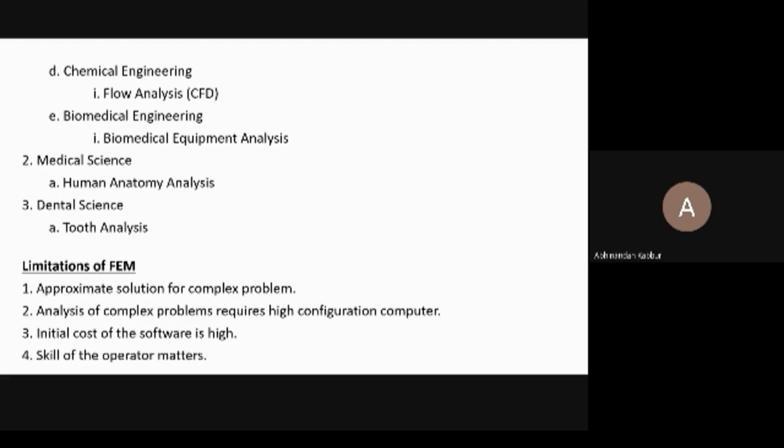And coming to the last limitation of FEM, we require skilled operators. That means see, if you give some input to the computer, it will give the output. The ultimate thing is we need to analyze that output, whether the output is feasible or not. If it is not feasible, what changes do I need to make? Whether I need to change the load, the material, or the boundary conditions.